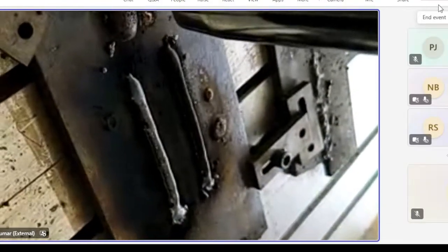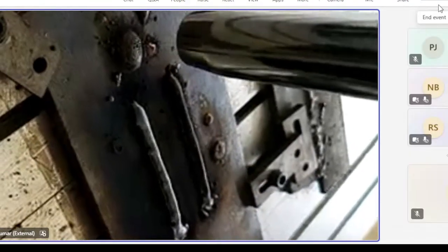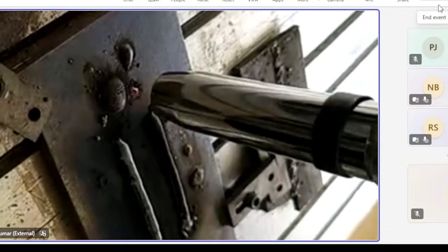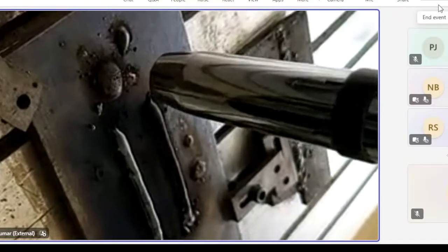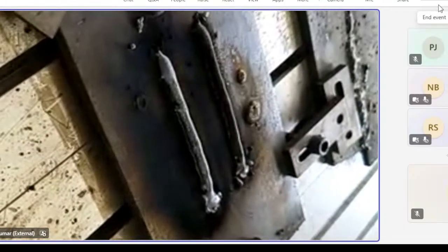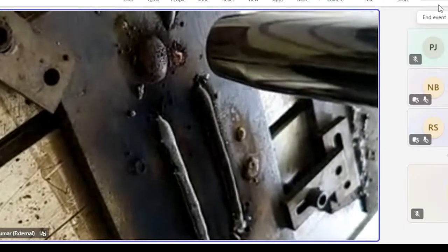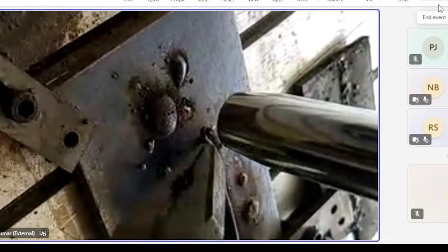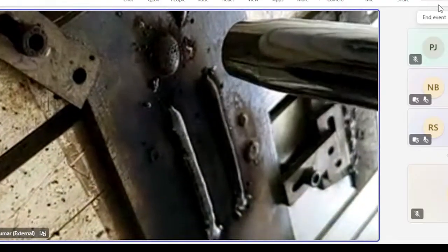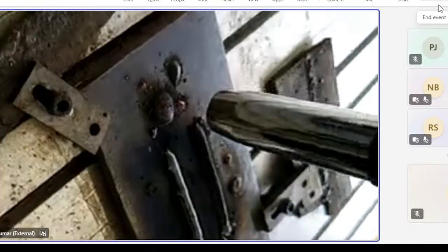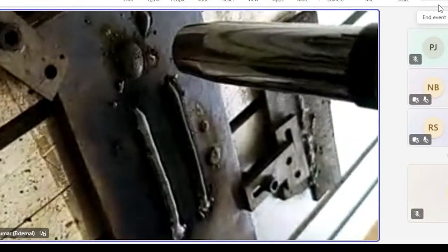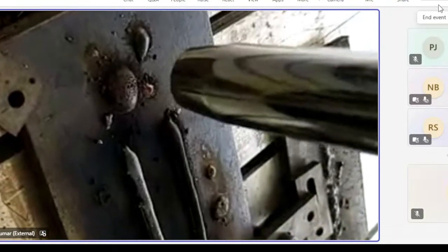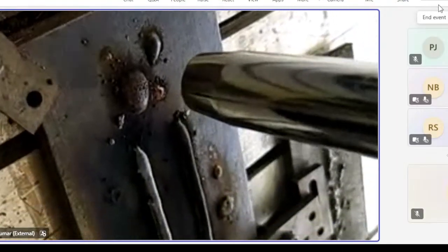If I want to deposit a complete wall, what we can do is either start the machine continuously from here to here to here. That means we move unidirectionally. And if we want to change the deposition strategy, then we can go bi-directional, like in the x direction, then again and again, with a continuous to and fro motion, and the deposition takes place. As we move on, the height will increase, and there is a chance of some defects like porosity and all that.